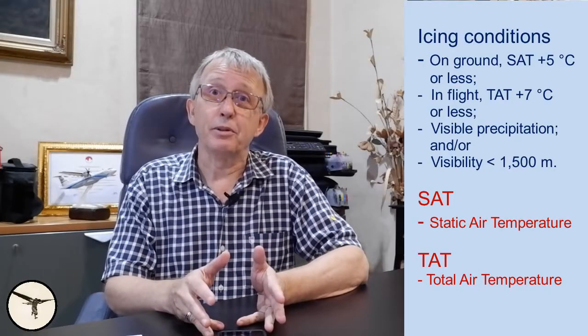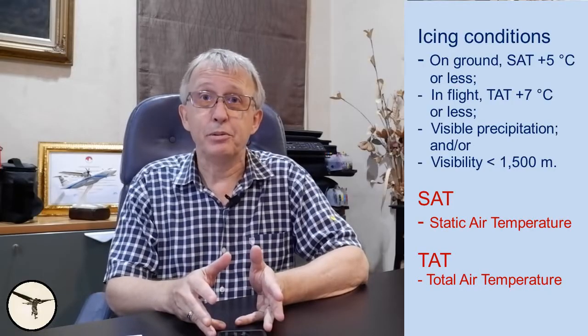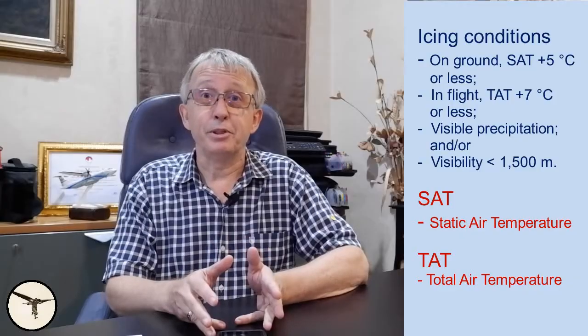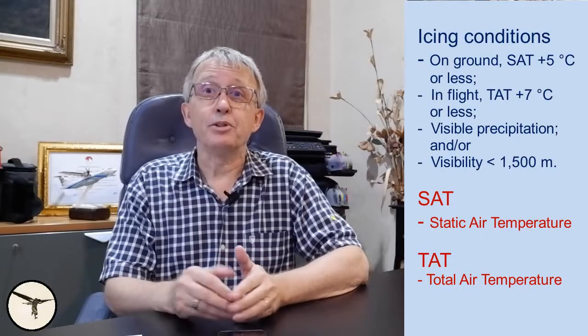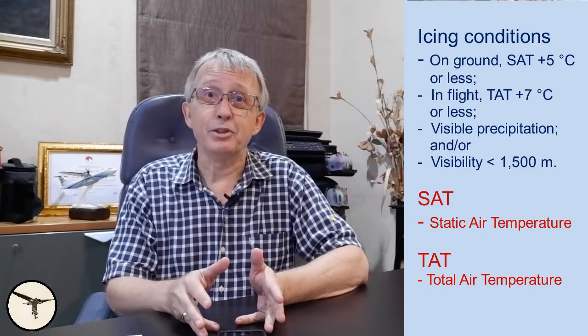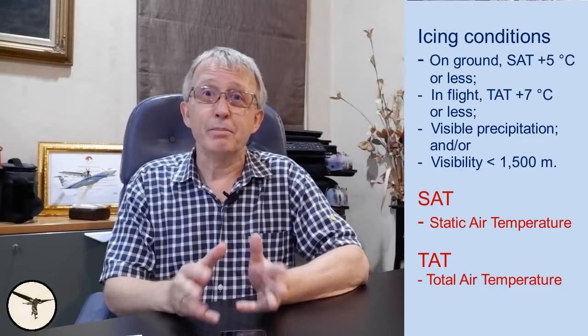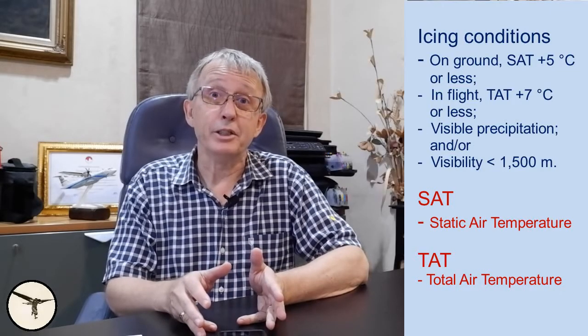Atmospheric temperature is called SAT, static air temperature. TAT, total air temperature, is SAT plus adiabatic heating caused by the increase of local air pressure, for example at the wing leading edge.